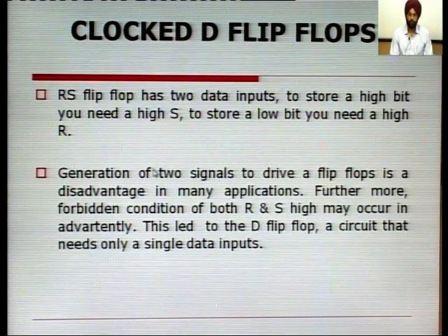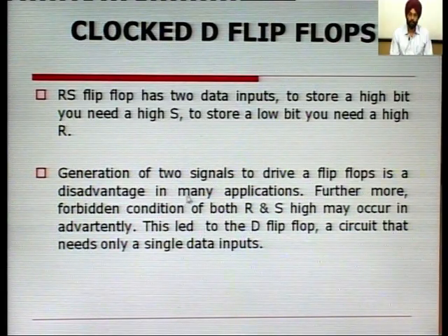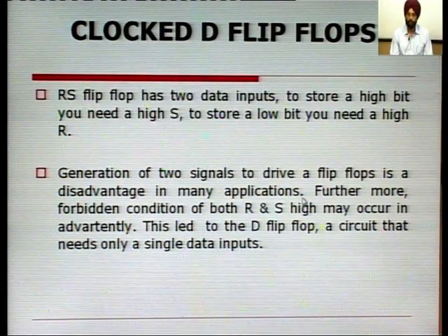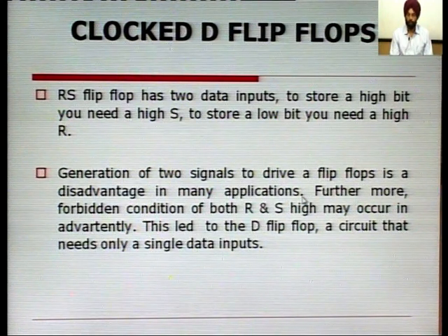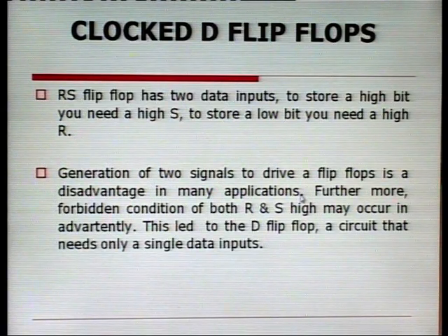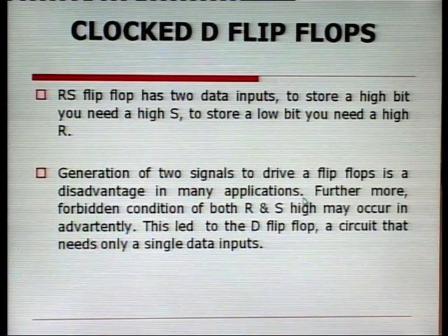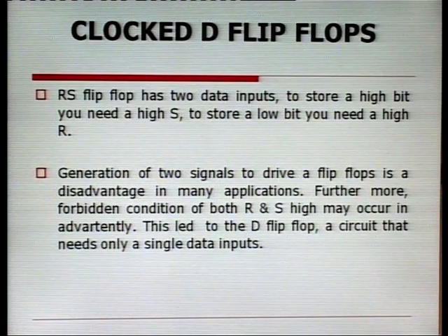Now, generation of two signals to drive a flip flop is a disadvantage in many applications, because in digital electronics like shift registers, we are using only one input, as a flip flop can store only one bit. So, in most applications we are using one bit only, one input only.